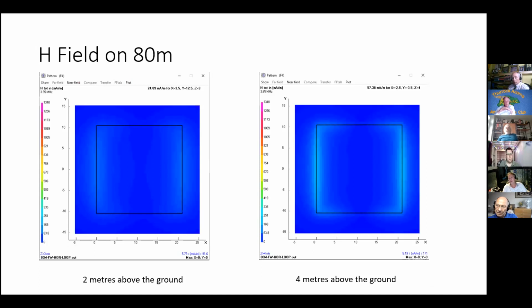The Ofcom calculator is going to be giving you answers that are more than two wavelengths. It will give you accurate answers. At the end of the day, two wavelengths on 23 centimeters is less than half a meter, so the boom is longer than that. Yeah, the boom's 3 meters. So you're going to end up probably, depending on the power level, with separation distances of the order of another 3 meters in front of the boom.